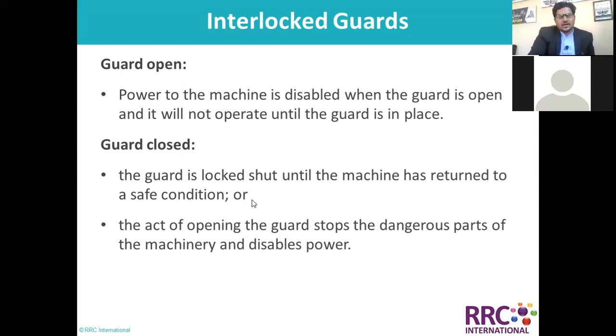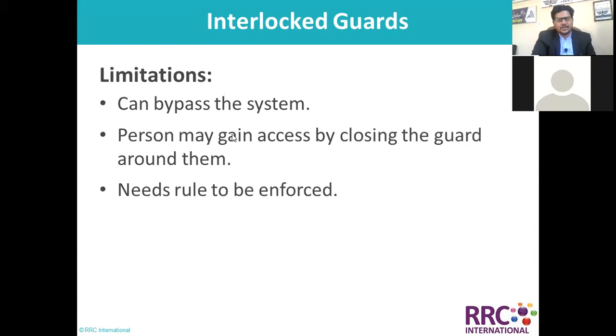Now guard closed: the guard is locked shut until the machine has returned to a safe condition, or the act of opening the guard stops the dangerous parts of the machine and disables power as well. Now these are some of the limitations. Can bypass the system. Persons may gain access by closing the guard around them. Need rules to be enforced.